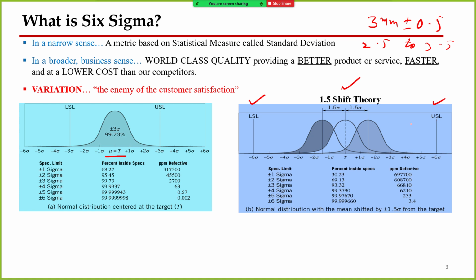the specification limit. Remember that whenever we talk about the specification limit, it is always based on the individual product. But when we look at our process and calculate limits, which are known as natural tolerance limits, they are calculated based on the mean of our process plus or minus k, the level of sigma, times the standard deviation. Natural tolerance limits are always calculated using this equation, as we can see here. This is basically our target point, or the mean value, up to that k level.